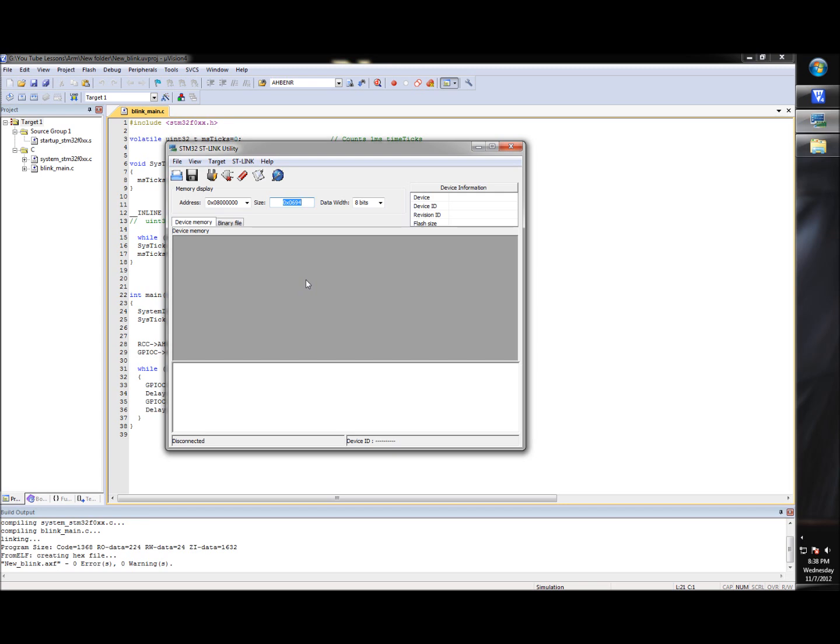Kind of like when we did in-circuit programming on the Microchip PICs. It's basically the same thing, and you can take those signals out of the board and use it as an actual programmer. That's pretty cool, considering this board is very affordable, under $10, and the MPLAB U2 programmer was, I think, over $100. You get a programmer for ARM processors for under $10. You can't beat that, so I highly recommend this little dev kit.